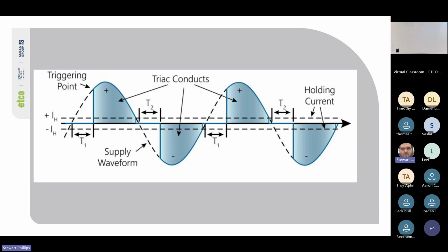And there you've got the two holding currents, but if you look very closely on the other sides of the waveform, we have a small cutoff on the back edge of the triac waveform as well. That's that little 5-volt cutoff from the diac.